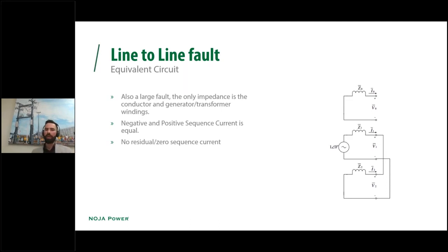In the case where your fault current for line to line is going to be close to the load current, negative phase sequence will still pick this up because you would assume under a healthy network that you have a relatively low level of negative phase sequence current. So it gives you a little bit of an ability to be able to identify line-to-line faults when your overcurrent is starting to reach what your load is, because the NPS is only looking for the imbalance. It's not looking for the total magnitude of each individual phase.